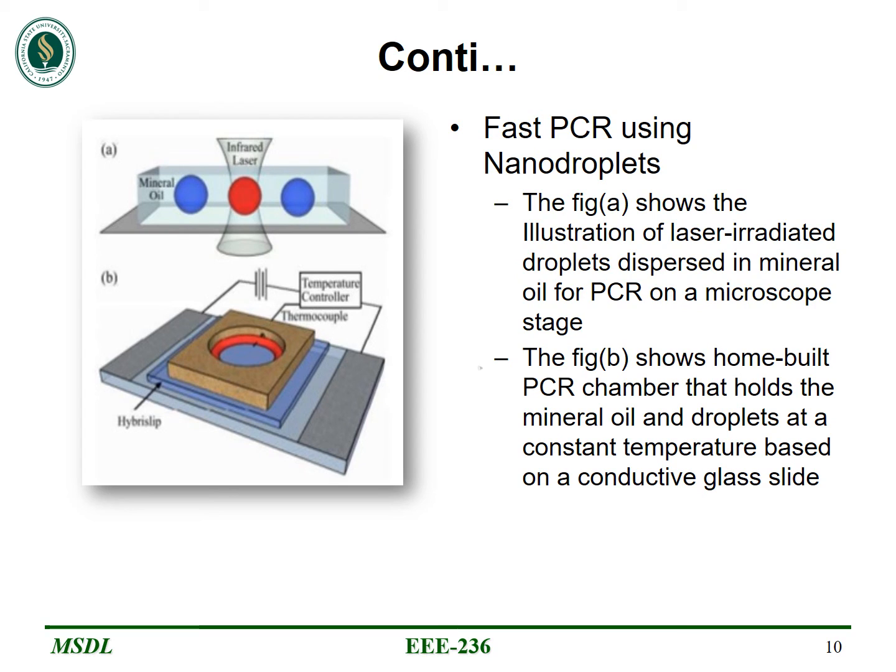While infrared heating for PCR can be performed with conventional light sources, a laser heating method can provide higher intensities and better power and wavelength control. Moreover, the same infrared laser that we used previously for droplet movement and mixing can also be used to drive the heating cycles of PCR on the platform. Another complementary advantage of the droplet approach is that the size of the droplet is easily matched to the short extension length of the infrared laser in water, thus following the trend of miniaturization while also optimizing the efficiency.